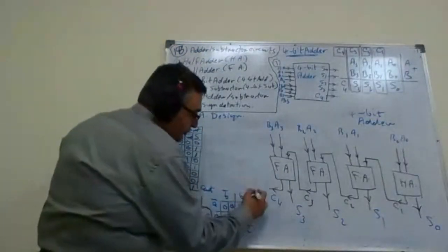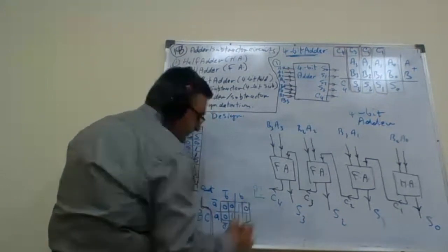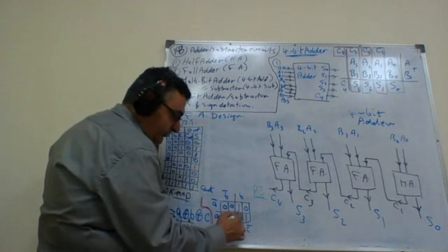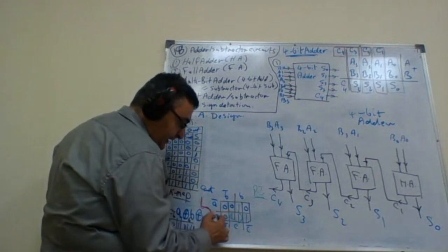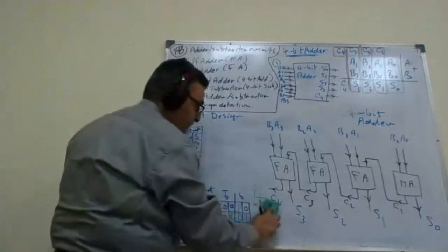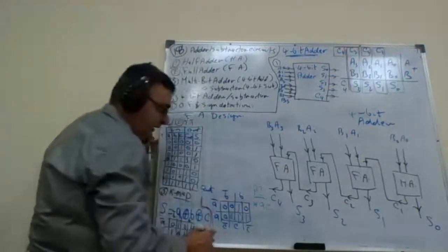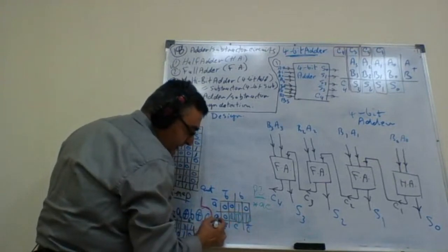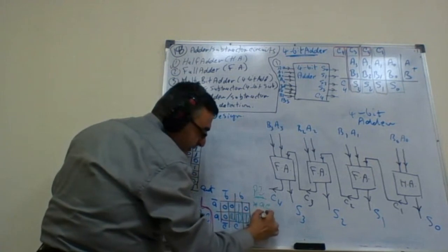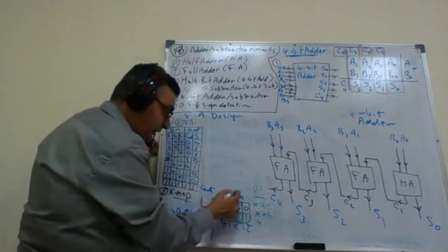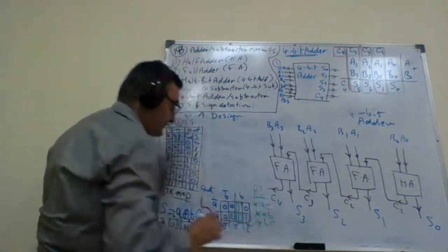Now I need to discover the prime implicants. So I have this prime implicant for this contour. This contour is AC. So I have the first, AC. Then I have the opposite one for those two cells. This is AB. I have AB. Finally, I have this contour. This is for BC. So I have BC.